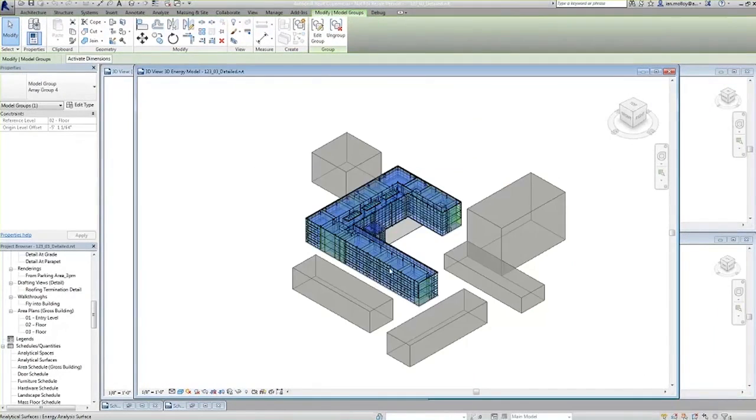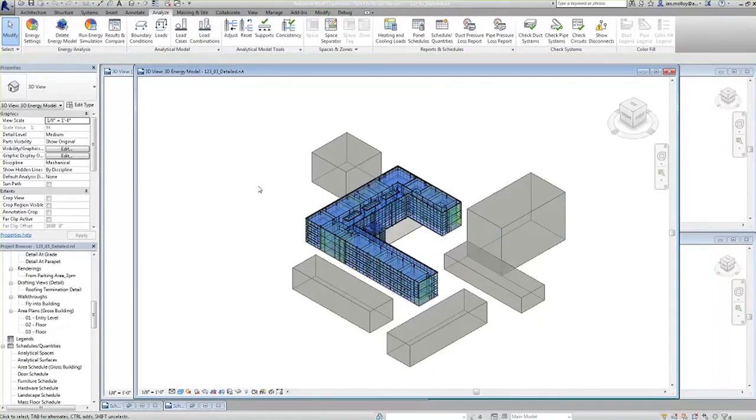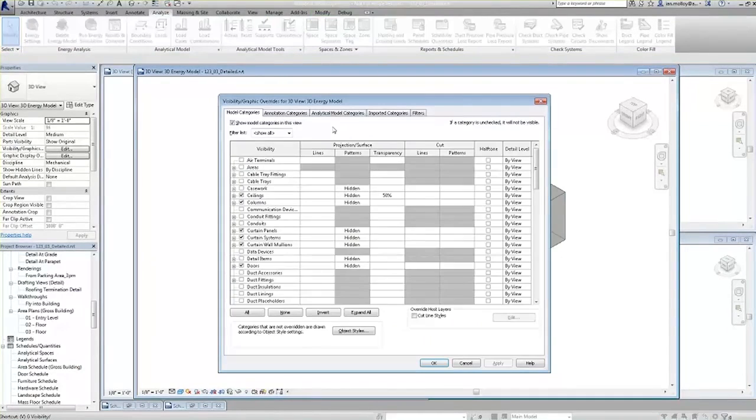This is the analytical model that gets created from that. And again, literally all we needed was for it to be reasonably enclosed. The only other thing I mentioned was this thing about appropriate resolution. That's just something that you try once, and if it doesn't look right, you can just dial it down. So basically, the more detailed your model, the higher the resolution you need to set. And it's very quick. You can visually check how quickly that is. And so again, here we can see in this model things like the analytical spaces. I'm just going to turn the architecture off.